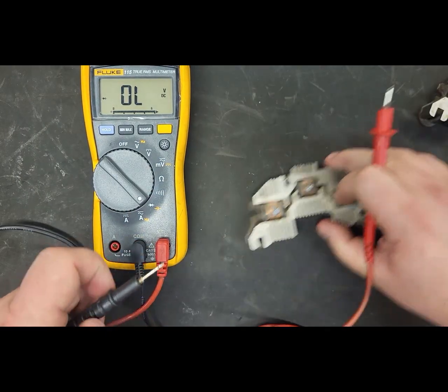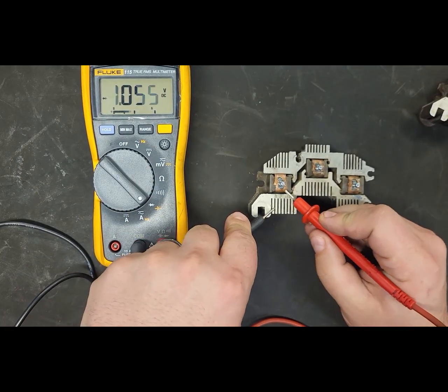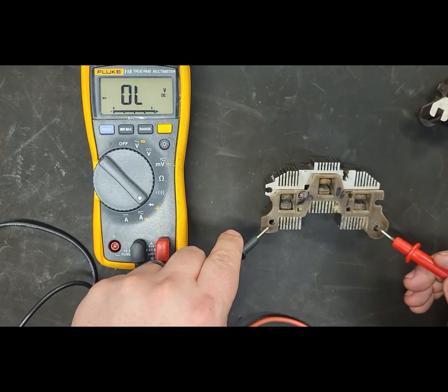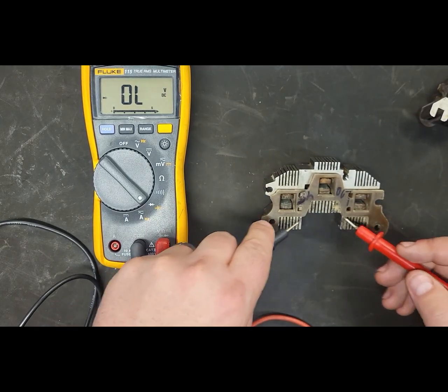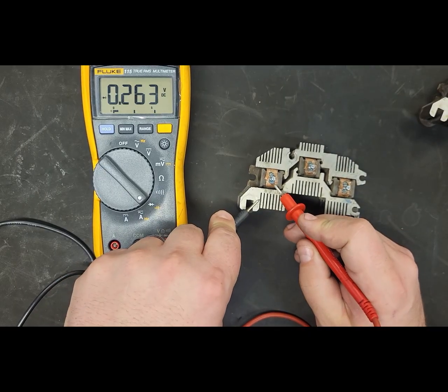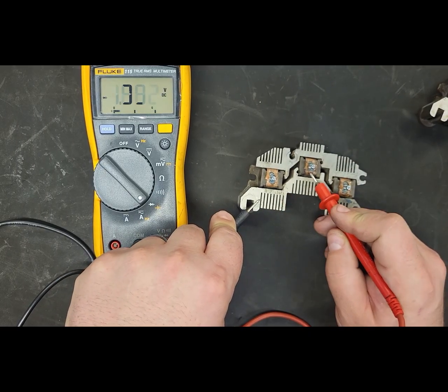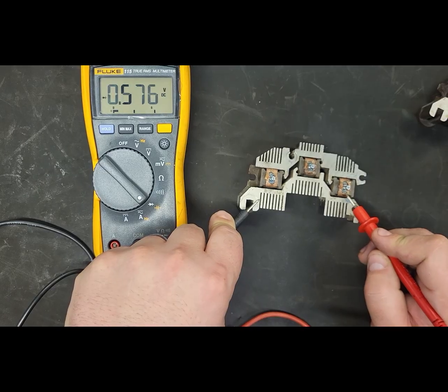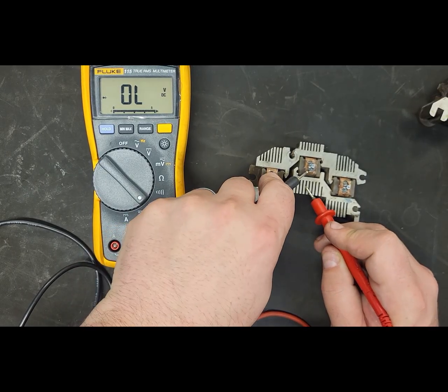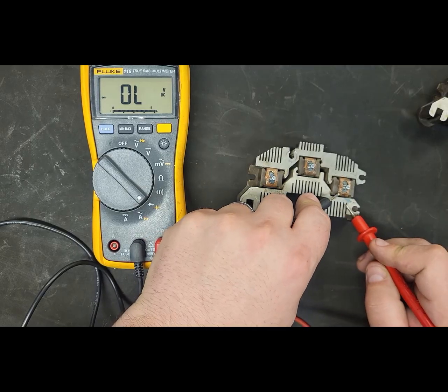This one is my messed up one. Okay, let's try this one. If I flip it over, I've got my 2 isolating bits here. This is my positive half, so I know the lower half is my positive half. This will put me in the forward bias. Okay, they're all good in the forward bias, and in the reverse bias, they're disallowing flow.